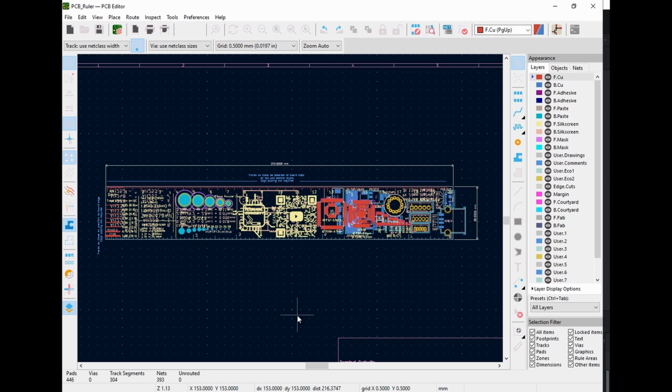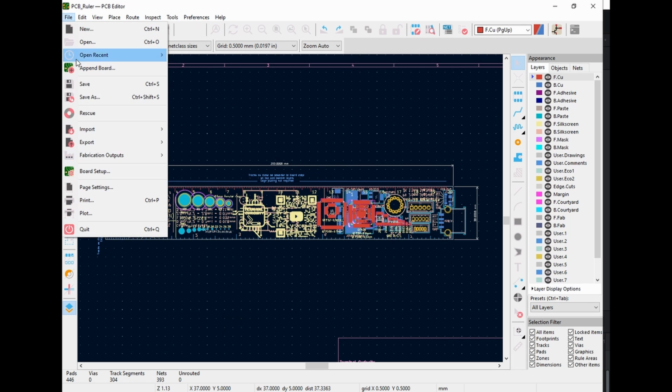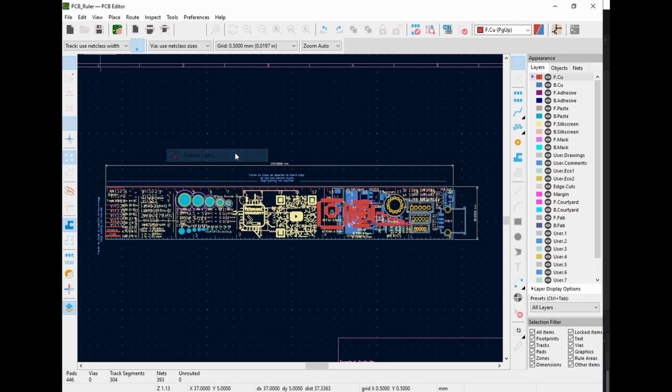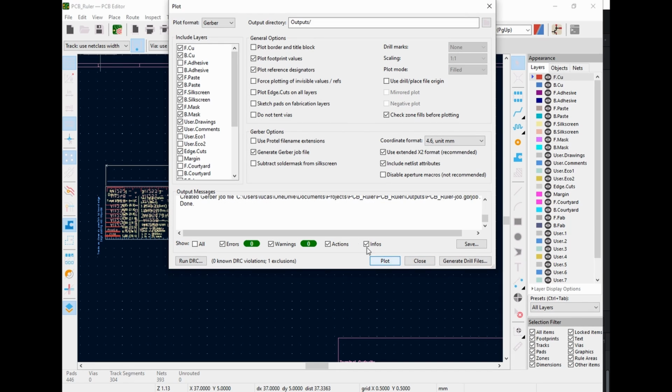The next step is to export the files for the manufacturer. So we go File, Fabrication Outputs, Gerbers. And if I click Plot...